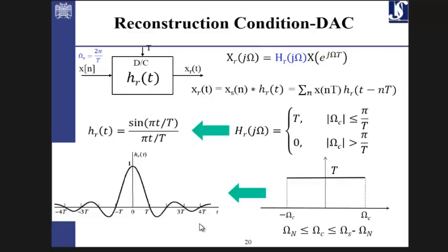If you have, for example, a speech signal, which makes sense to have frequencies from 0 to 4 kilohertz, what is the minimum frequency of sampling in order to get the signal back without any errors? 8K. 8,000 is the minimum frequency you need if you want to get the entire signal back.